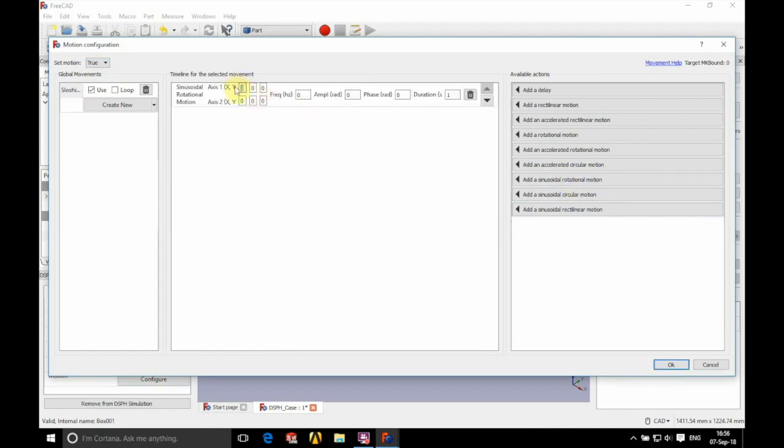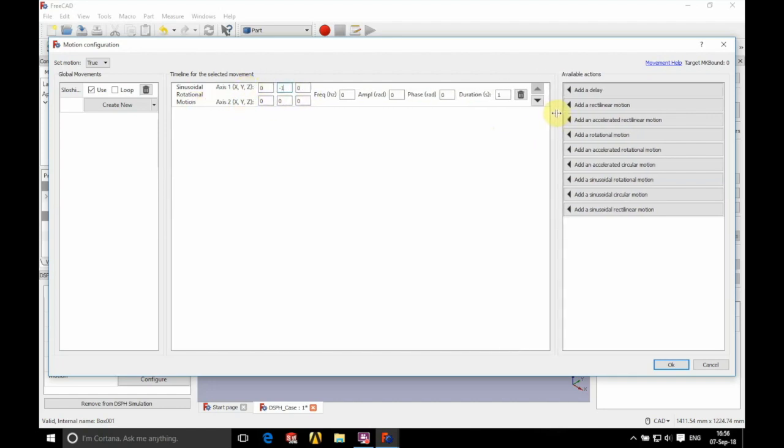So we're going to have our tank rotate between -1 in y and 0.25 in z, and then 1 in y, and again 0.25 in z, with a frequency of 0.5 Hz and an amplitude of 0.14 radians, and with a duration of 5 seconds.